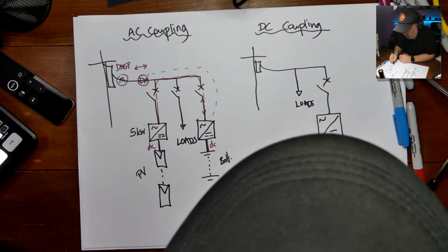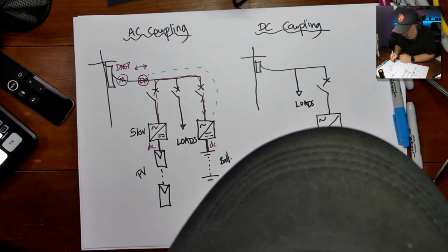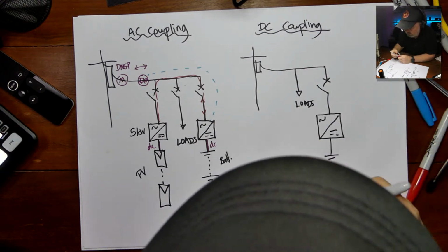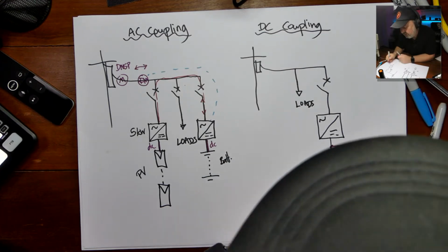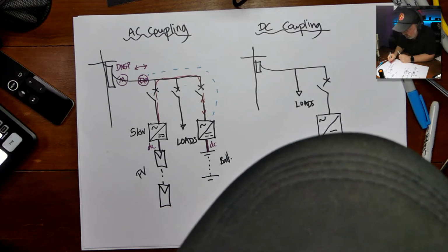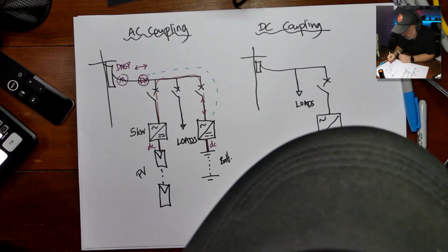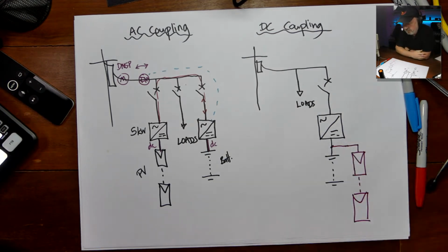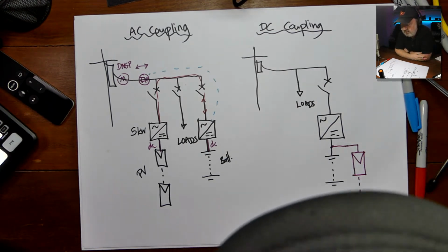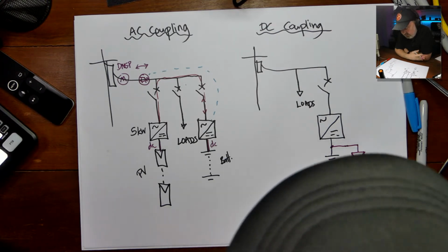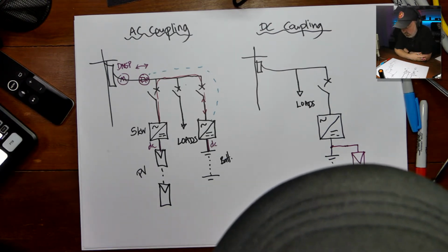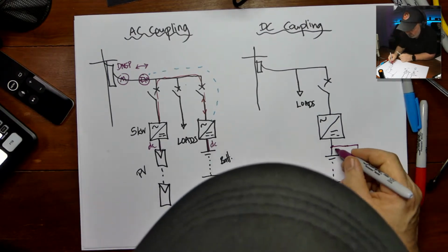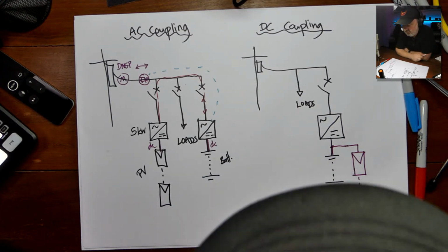But this battery inverter also has solar connected to it. So the solar is connected onto the battery terminals, basically, or within the inverter there'll be what's known as a DC bus, and it will connect in there as well, possibly. So it depends on the configuration of the system, whether it's an external connection or not. Now, this might be pretty basic stuff for installers. Don't worry, we're getting through to the more technical stuff, but I'm just ramping it in there a little bit, not going too fast, too quickly. So this is a DC coupled system, and the reason it's called DC coupling is that the DC energy gets into the battery directly. It doesn't actually have to go through an AC network.